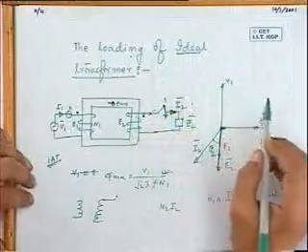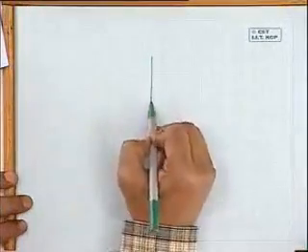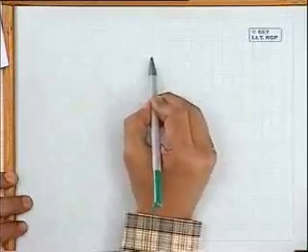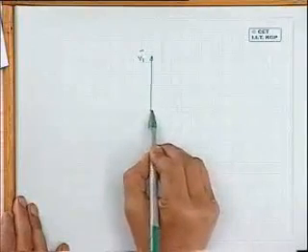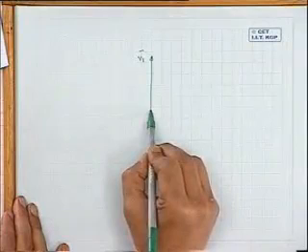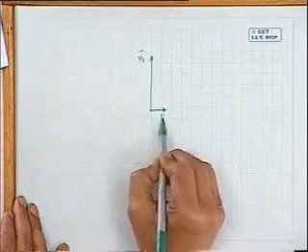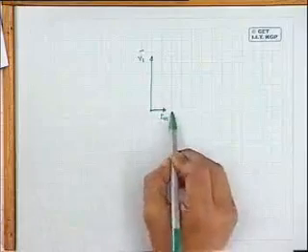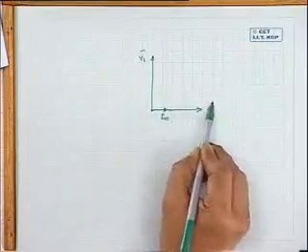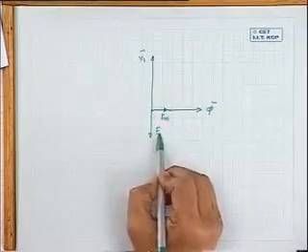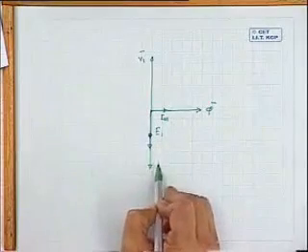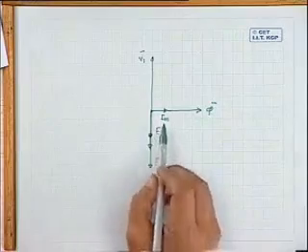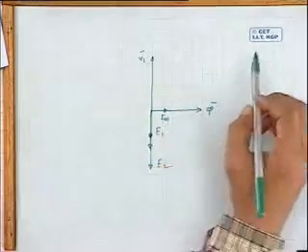Okay. I mean, to tell you, I will slightly digress from this ideal transformer. Let us put it also in this way. Suppose it is not so ideal a transformer. I am slightly digressing from the ideal transformer in this sense, so that those problems do not remain in your minds. Suppose it has a finite permeability, so it was drawing some IM, magnetizing current, under no load condition, and it developed a flux phi. There was induced voltage in the primary, E1, which is the same as V1, and there was a secondary voltage E2.